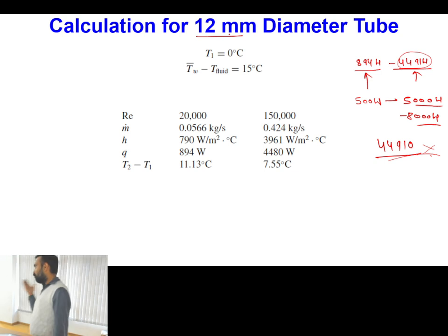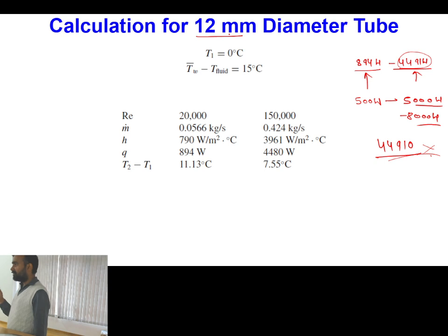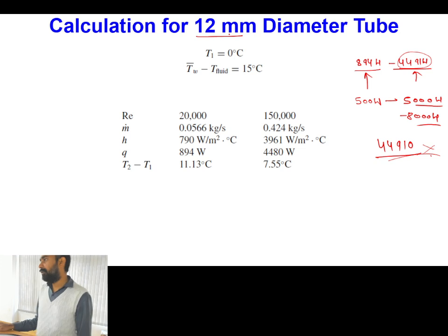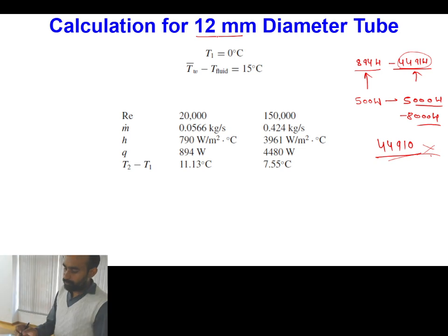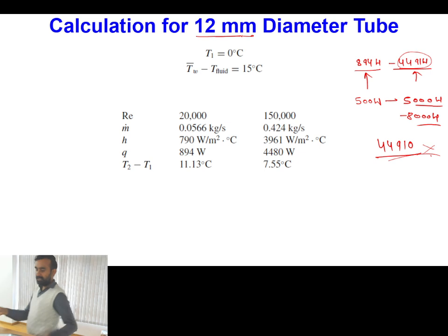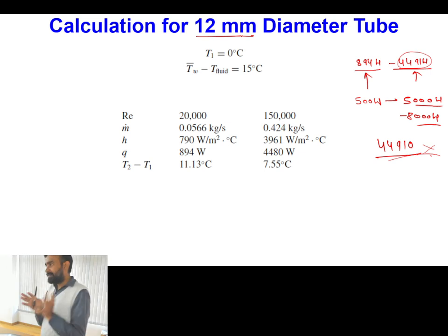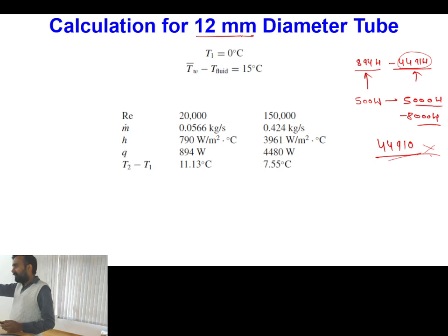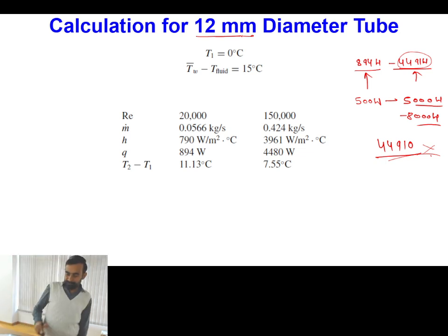Okay, so typically in your home refrigerator and air conditioning units, you will find the tube diameter majorly ranges from 8 mm to 12 or 15 mm. So the availability of this tube will also be easy. So we have frozen the diameter as 12 mm. Of course, I am not saying that everyone has to freeze the diameter as 12 mm. You may go to 15 mm, 20 mm depending upon the availability, but it has to be within this range, and try to take some mid value so that it covers almost the spectrum on the lower end as well as on the higher end.